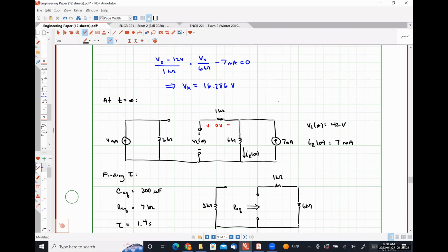No, but for that particular problem, you're just doing transient analysis effectively twice. You do your transient analysis when your switch opens and it behaves one way, exponentially decaying until the next thing happens, and then you have a new transient system. That's all it is. So it's just different conditions essentially.